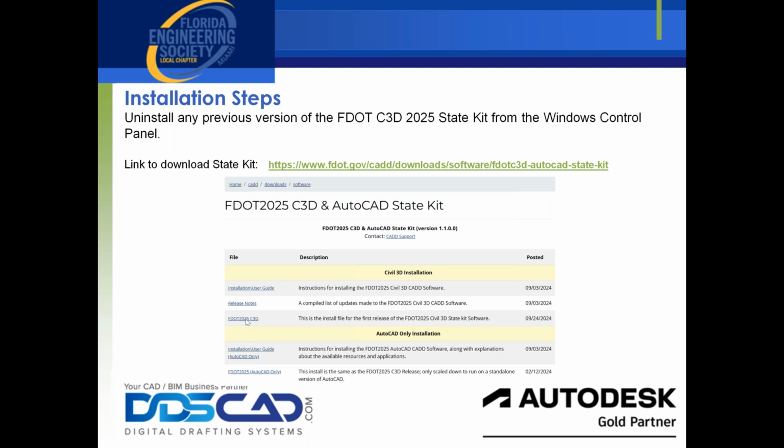And then when you create that file, it's going to go into, in this case, the survey folder underneath whatever project you created it in. So yes, to play with it, you can just create a fictitious name like all ones, just to create the project. But you have to use the Create File tool in order for it to create that project and then create the DST file that it needs. Those DST files are typically used when you get into creating your sheets for outputting, so it helps fill in your title blocks, the best I remember.